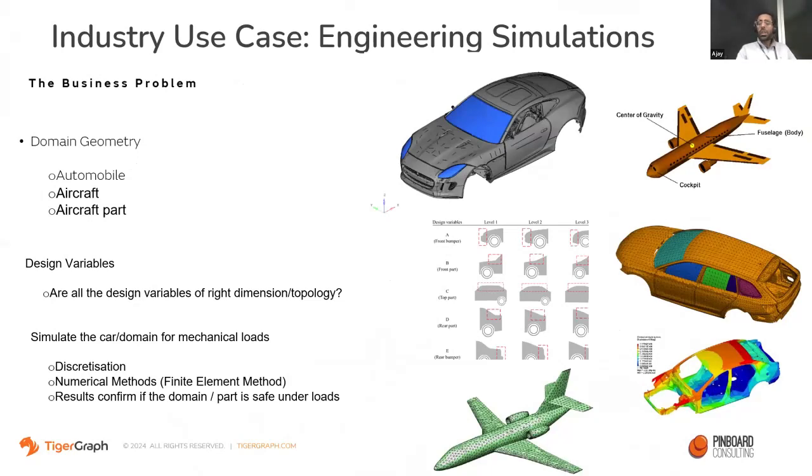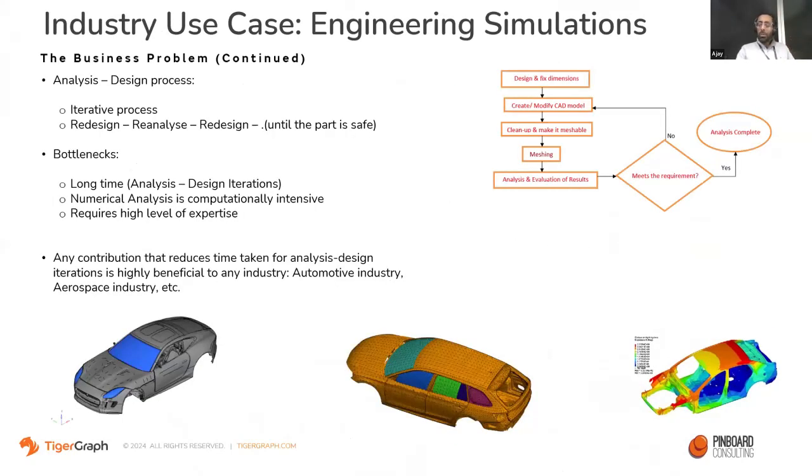that it cannot withstand the load, it's an iterative process, because I again refine my design. I change the dimension of the part, and I change the thickness of the part. I redesign it, discretize it again, take it to my computational software, and redo the whole simulation.